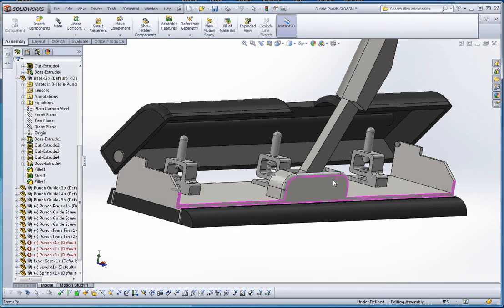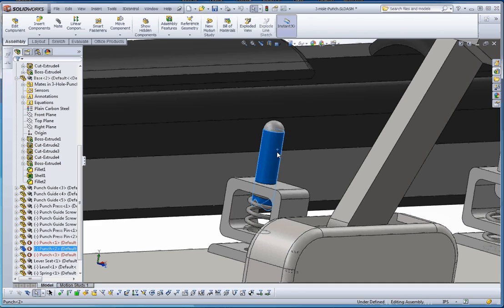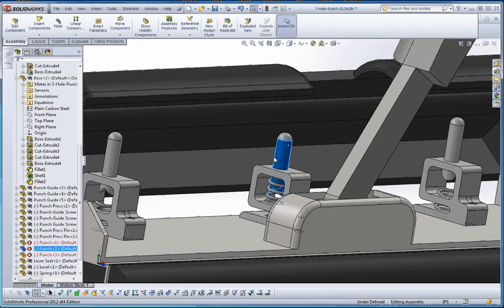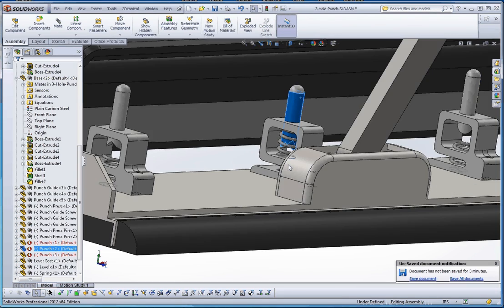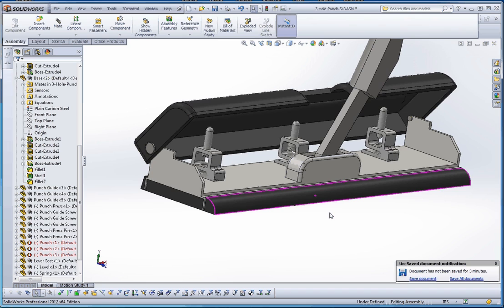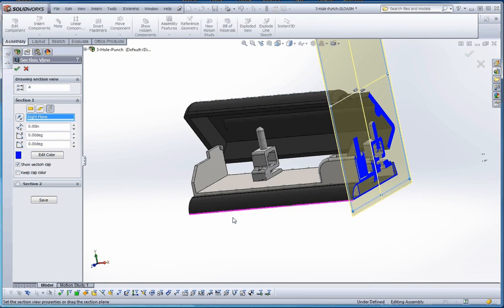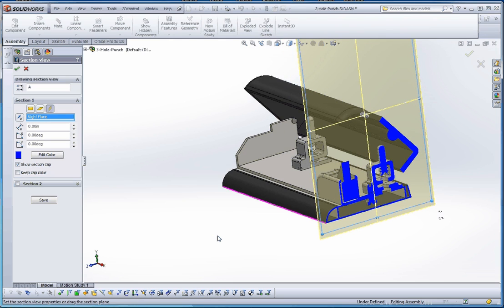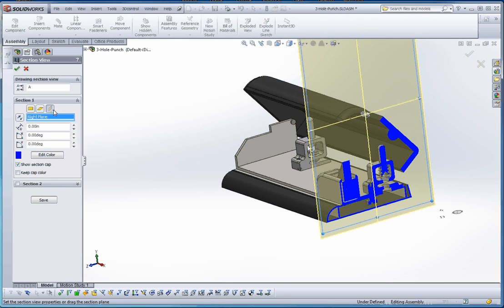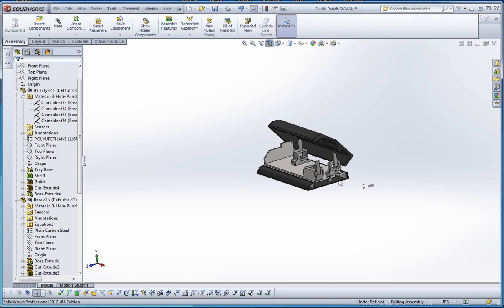And now you have the tops of your punches in here, and that should go down through the cylinders that you have down here, the cylindrical cuts. So let's do this. To help us model, let's go to a section view, and let's take a look at that right down the middle of that. And you have a couple different choices over here with your section views. We're going to choose the one on the right, and what that does is just gives you a different 90-degree orientation. Go to the green check mark.